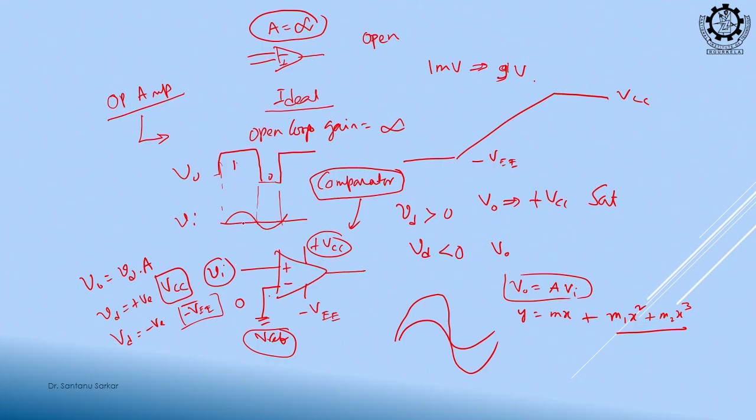This 0 is a DC level, right, that you can change, understood. So, if rather than 0, it is now x, the moment the input crosses x, then I will get a 1, clear. So, that is one problem of an open loop amplifier.